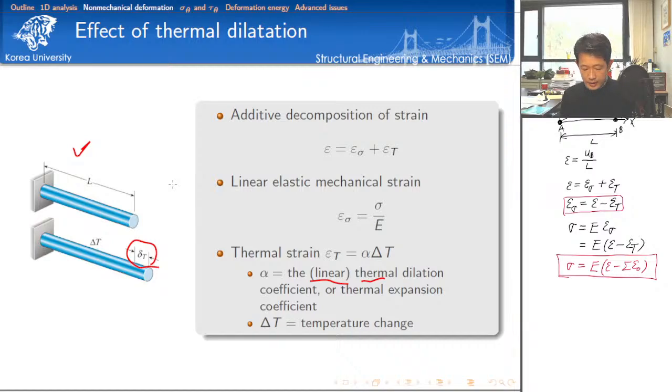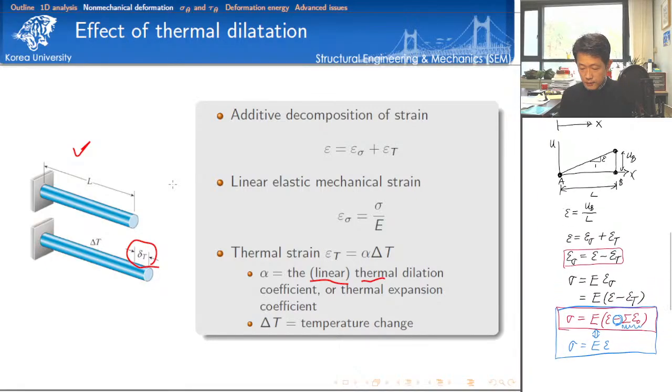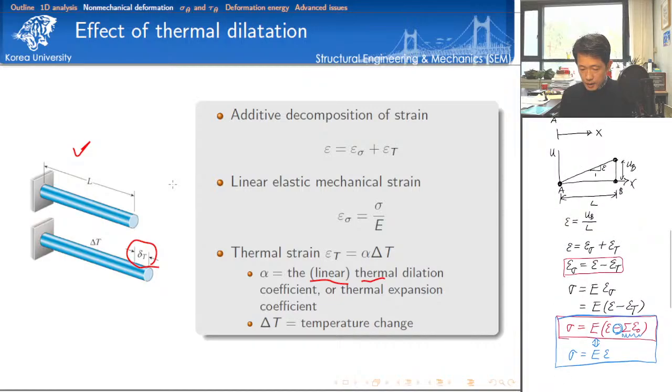Okay. So last time we had what? Hooke's law, the stress is equal to elastic modulus times strain. But make sure that this Hooke's law is extended to include non-mechanical strain with a minus sign here. This is an important point that you need to understand. Once you understand this, we can consider the force equilibrium. So let's talk about the force equilibrium.